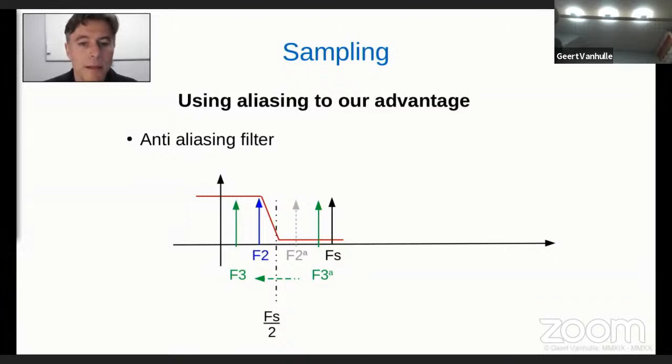So between half of the sample frequency and the sample frequency, what we have is a signal rise in frequency. They are mirrored as a frequency that is closer to 0. So we get a flipping of the frequency spectrum in this range. So this is something to remember.